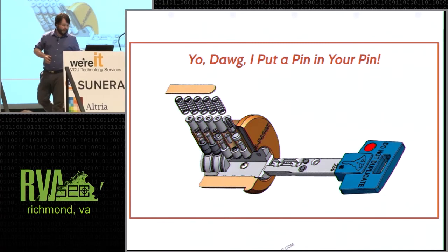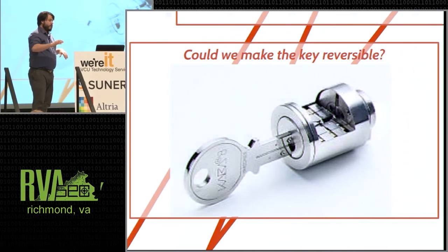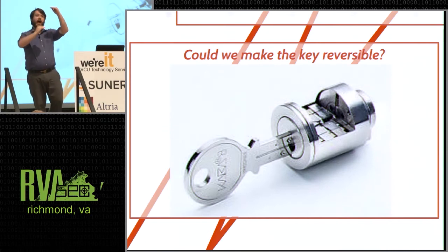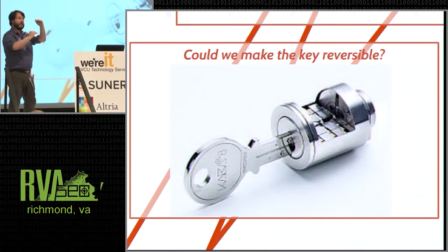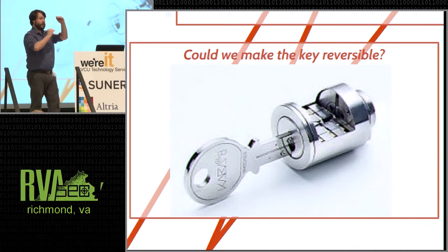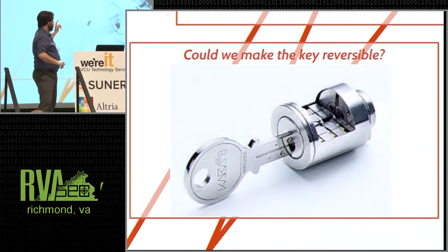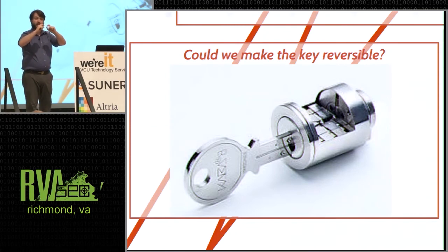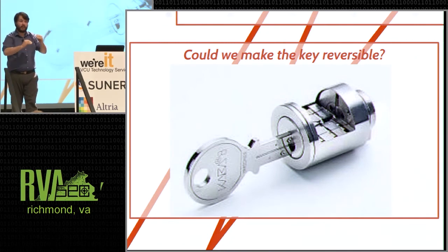So dimple locks in general have a problem. If we look at the Kaba again, think about a key blank and a normal pin tumbler lock. When you have a normal pin tumbler key, you have some valleys cut into the key, some peaks, whatever. The possible variations contribute greatly to the security of your lock. The bigger the range of differences in your key, the harder it will be to pick. When you're cutting into the blade, into the flat of the key, the possible distance traveled is very, very small. So the maximum difference in height between the different pins is very shallow.